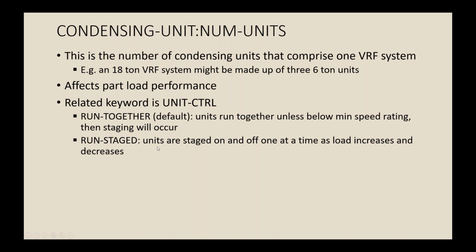Run stage, on the other hand, is more of a strictly staged system approach, and each one will still have variable operation capacity, but they'll stage one on and off one at a time as load goes up and down.